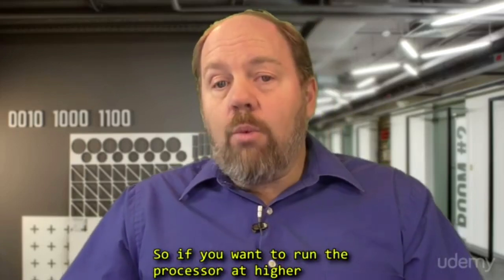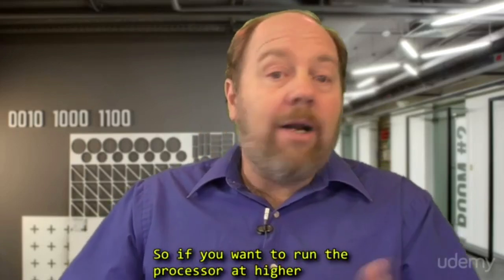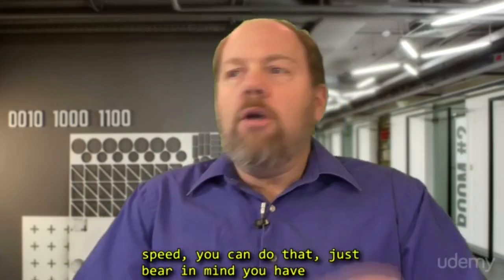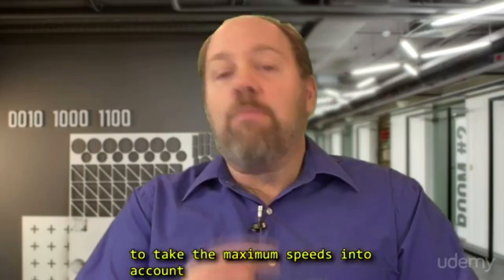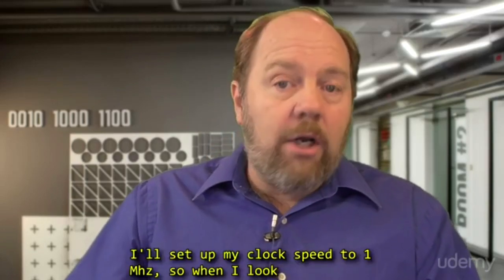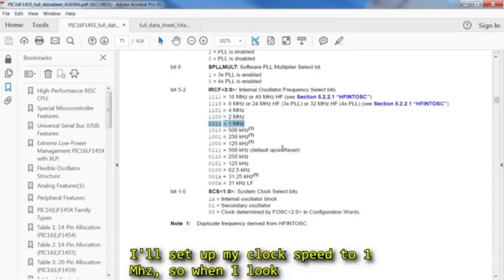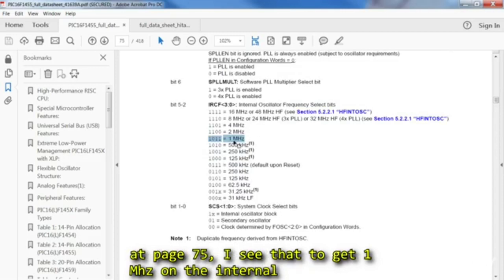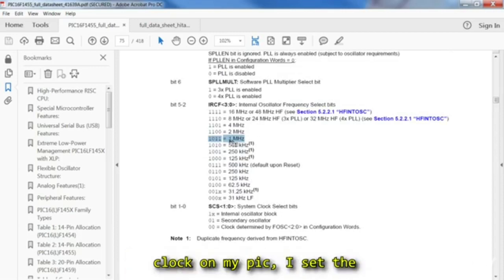So if you want to run the processor at higher speed, you can do that. Just bear in mind, you have to take the maximum speeds into account for the display. So I'll set up my clock speed to 1 megahertz. So when I look at page 75, I see that to get 1 megahertz on the internal clock on my PIC, I set the OSCON internal oscillator frequency select bits to 1011.